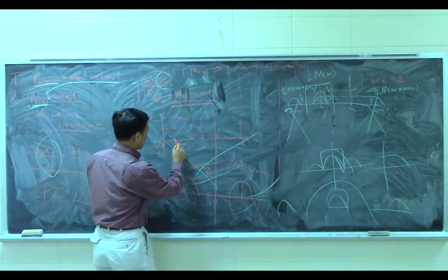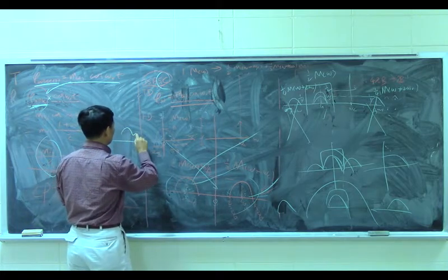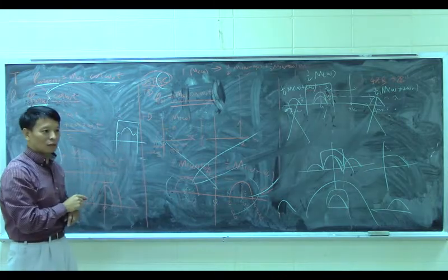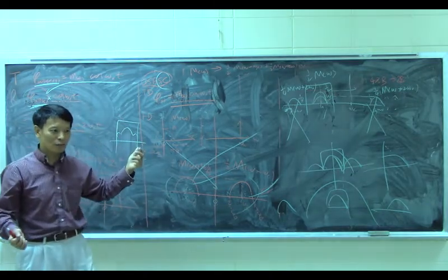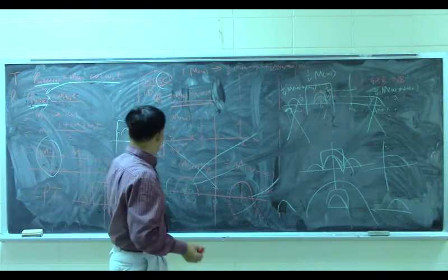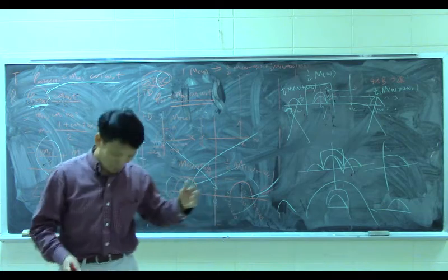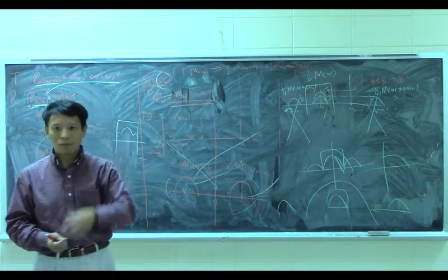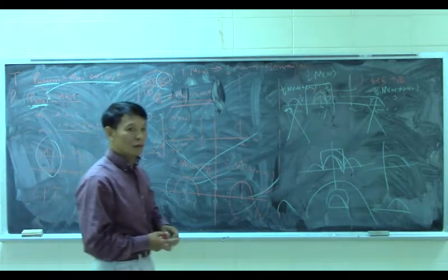If you have high frequency added to here, your spectrum will look like this, so the low pass is blocking out. What you have will look like this. See, this one is not exactly this one. So you are going to have distortion. The music you hear here is not exactly the same thing. It has garbage noise inside. All the voice is also distorted.